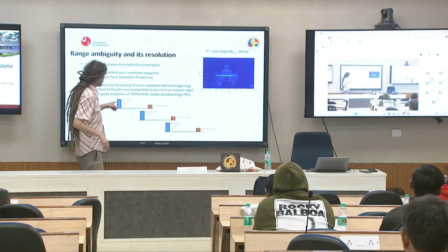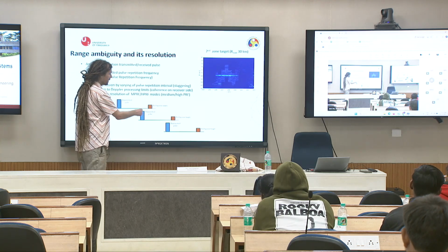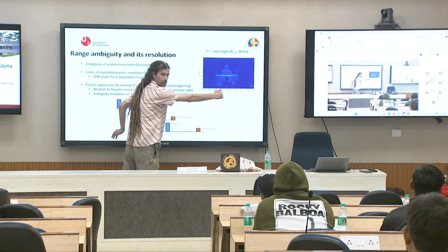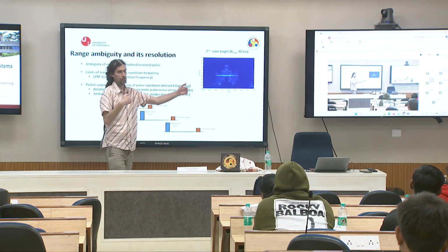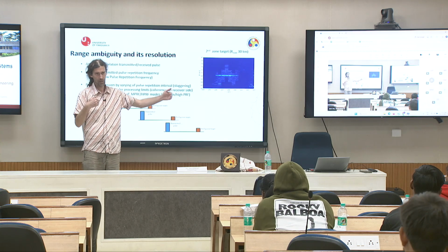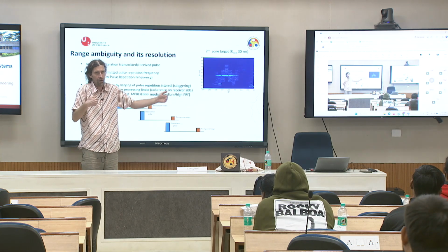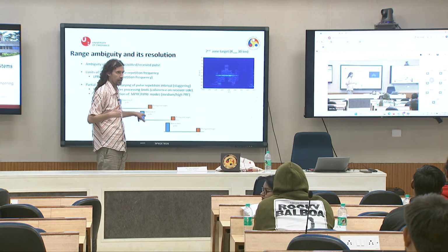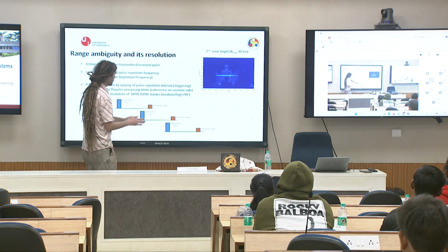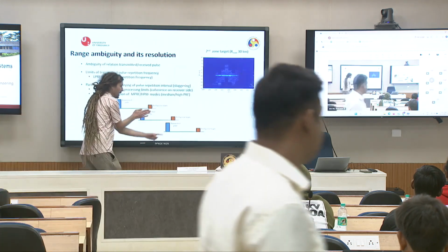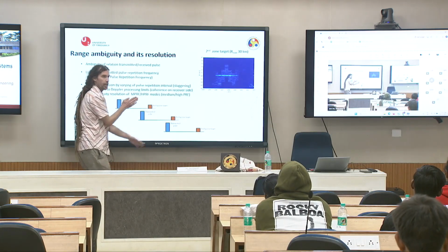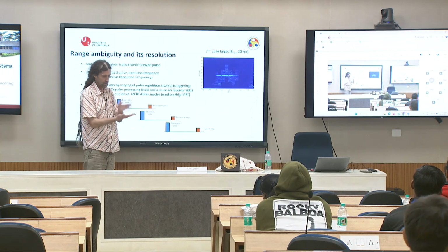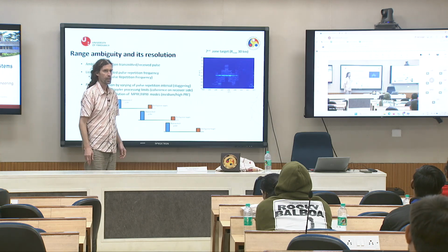So how can we avoid this ambiguity? I will make a higher interval between transmission pulses. Is it right? Yes. If I wait a longer time before I transmit the second pulse, this one will not be there, but I will send this and then this, then it will be okay. It is unambiguous. It will be a clear message where the target is.